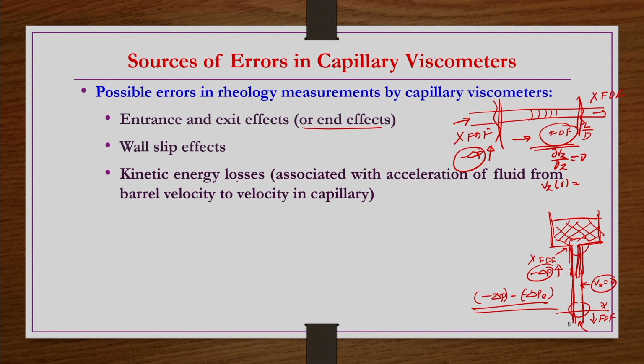Then kinetic energy losses. What happens when the fluid is accelerating from this barrel or vessel to get into the capillary and then get out of the capillary? There is a kinetic energy loss, obviously, and how important is it? Then when the fluid is going out, the fluid head is gradually decreasing. When it is decreasing gradually, how much effect is it going to have on the rheology? That is the other thing.